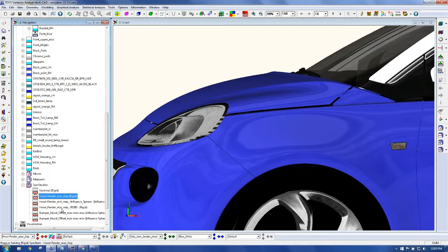It's very fast. Now, talking about bringing it into DeltaGen and bringing it into our high-end visualization tool, the background image. Where do I get the background image from? Most of your visualization tools are going to come with what's called an HDRI, which is a high dynamic range image. It's set up into a dome or sometimes even as a back plate, but it provides the main portion of your lighting, and those can be purchased. There's many places online that have fantastic HDRI images. Just to note, they're not cheap.